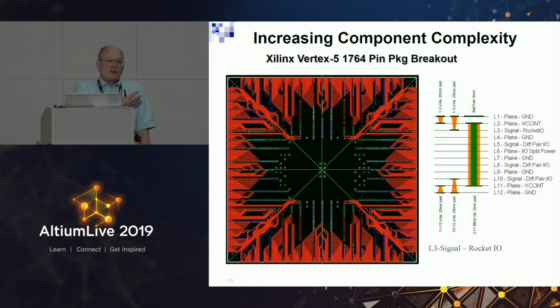And we're already working with a reduced noise budget on these more modern chips. They're down to 3.3 volts and sometimes only 1.3 volts total voltage, and our noise budget has shrunk enormously. So we've got signal integrity and noise issues all over the place, so we want to isolate our most critical nets. As I'll get into, our most critical nets are always in the HDI zone, and our less critical nets are in the center of the board where there are lots of through holes. So I'm a big advocate of annotating the schematic by the sensitivity of the nets, in terms of what electrical class each set belongs to.